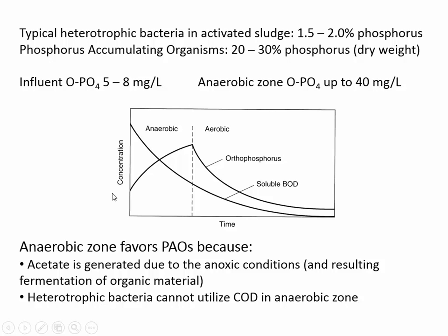So how come? Does anybody remember, why does the phosphorus concentration temporarily increase? Because when they get to the anaerobic tank, they're releasing the phosphorus. Right. And then they're releasing the poly into ortho. So, and ortho is soluble. And then here in the aeration basin, you can see that they're using up the ortho out of the water, turning it into polyphosphorus.